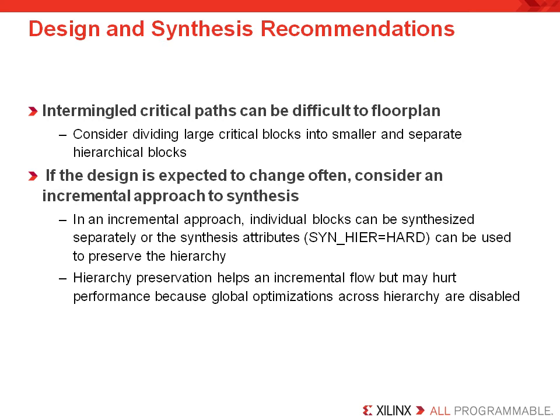But if your design is expected to change very often, consider an incremental approach to synthesis. In an incremental approach, individual blocks can be synthesized separately, or synthesis attributes can be used to preserve the hierarchy. Hierarchy preservation helps an incremental flow, but may hurt your performance since global optimizations across hierarchy are disabled. You may need to consider the trade-off before you embark on any incremental RTL synthesis methodology.